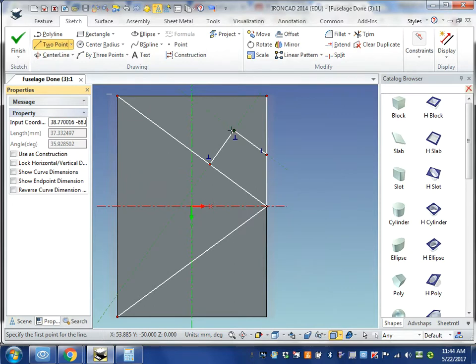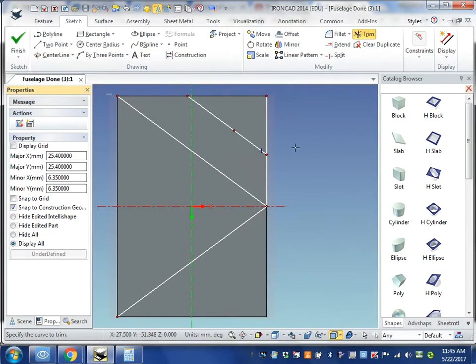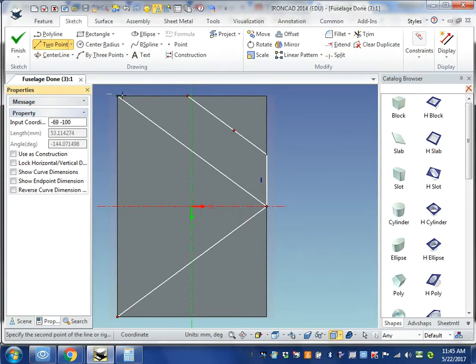Okay, now I'm going to do a green line straight forward. As soon as you get that T showing you're at a 90-degree angle, that's where you want it. Okay. I'm going to use a trim command. I'm going to trim out this line right here. I'm going to trim off this line right here. I am going to use a 2-point line. I guess I could have put this one in earlier. We're doing right to here.